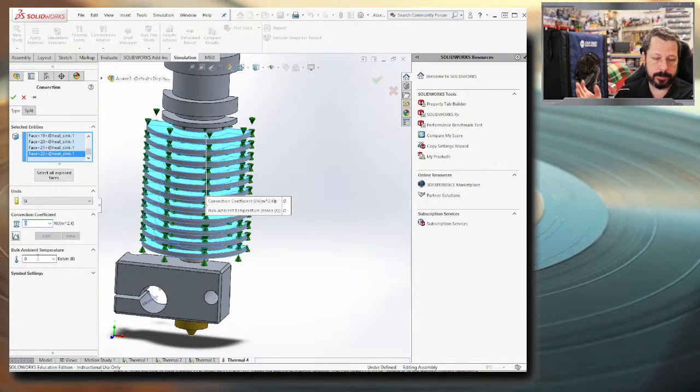Here's the ambient temperature right here. Well, let's not do 273. Let's do, I don't know, 290 Kelvin maybe? I don't get the choice to put it in different units. So let's use the lower end of our range, 20 to 300. This is going to be the lower end of our forced convection variable. It's probably higher than this, but I don't know what number to put in there. So I'm going to use the most conservative number that exists in the range of typical forced air convection.